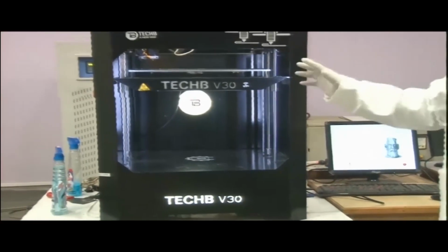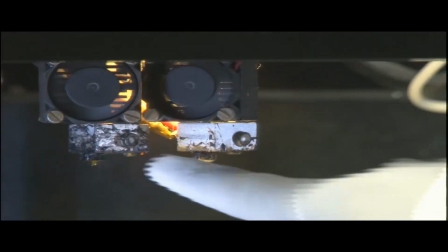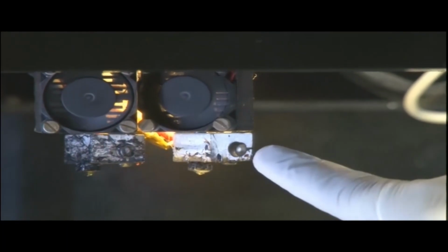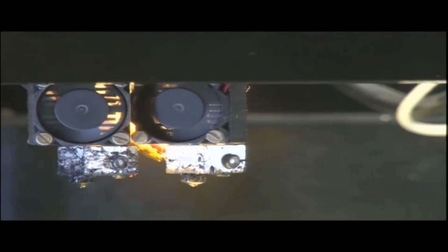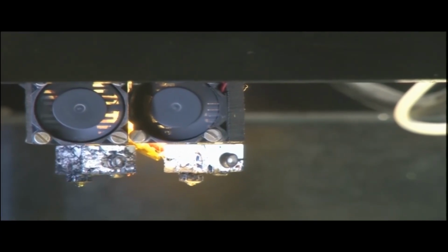So there are two nozzles, one for the model and one for support. If any profile or geometry has a taper of more than 45 degrees, we need to provide support, like I discussed. Then the two nozzles will automatically activate and provide the support to produce the final model that we need to obtain. All this feedback is given to the head with the help of software that will be described later on.